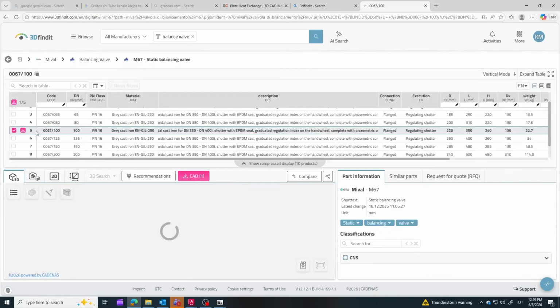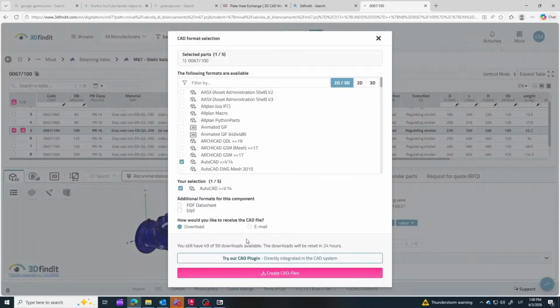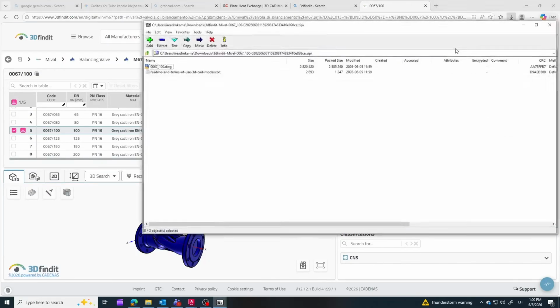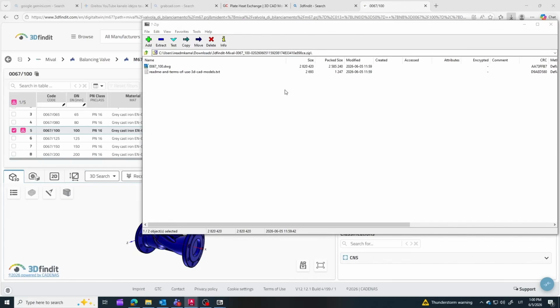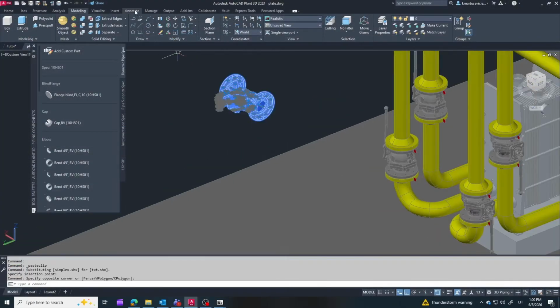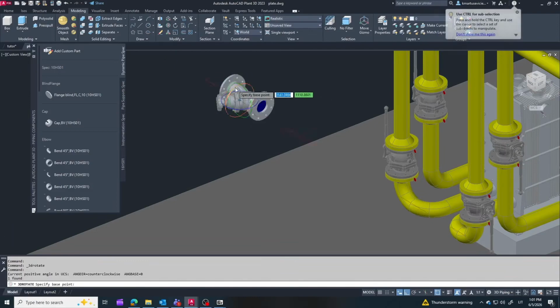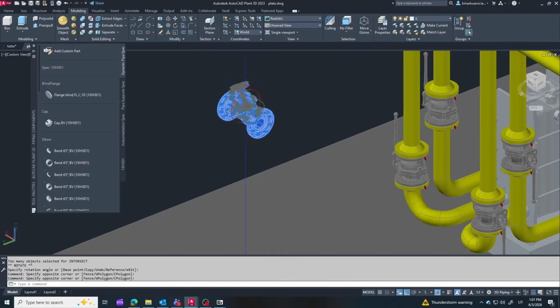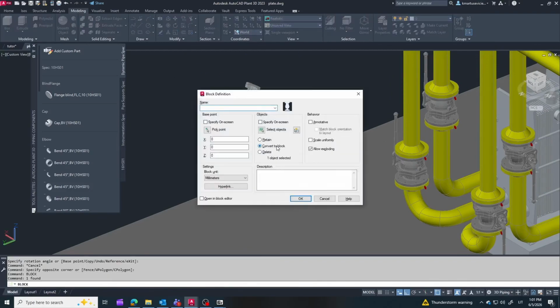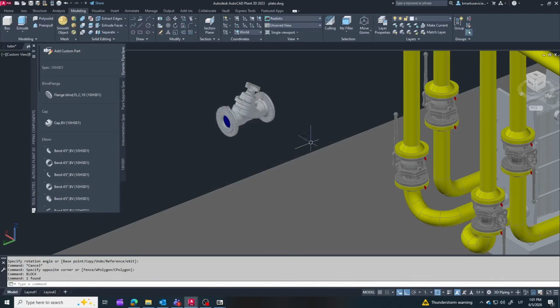You'll notice its distinct shape features small adjusting hand wheels right on the body. Its main purpose is to handle hydraulic balancing when you have multiple exchangers operating in parallel. Without these valves, fluid naturally takes the path of least resistance, starving some units while overloading others. By adding a balancing valve, we introduce controlled resistance, ensuring an equal, optimized flow to every single heat exchanger in the system.